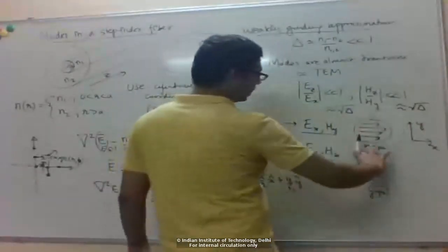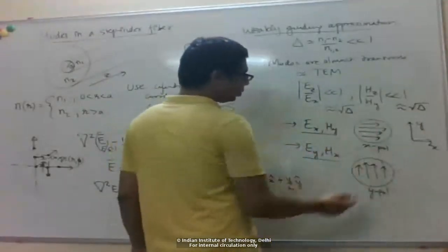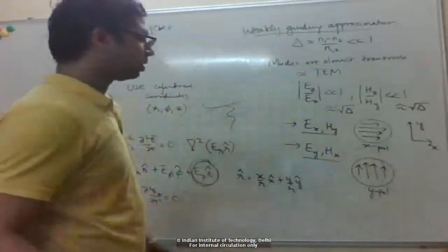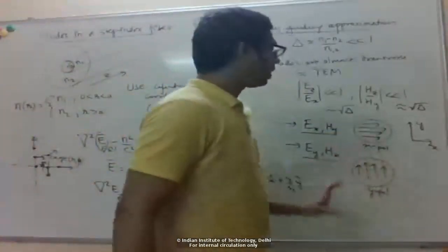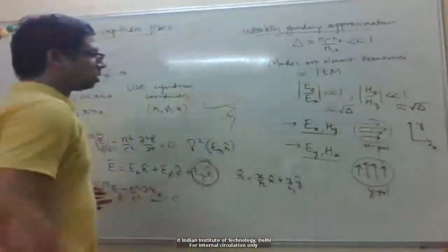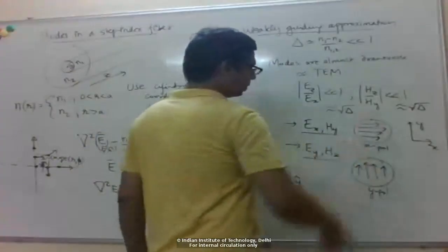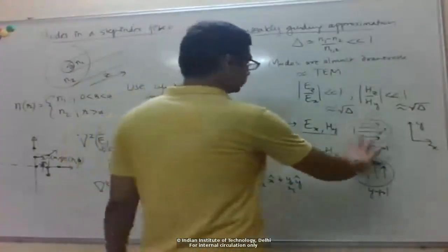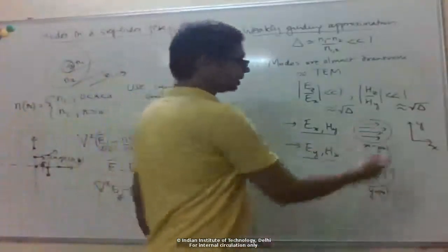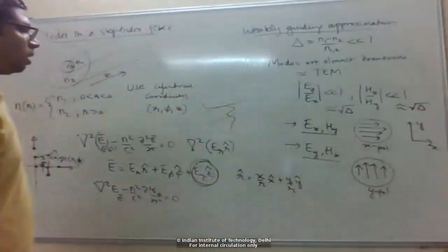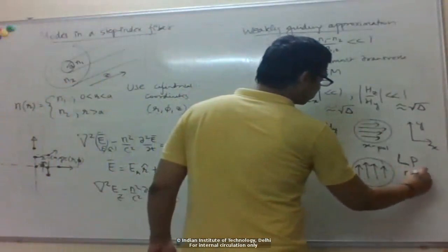Right, and because of this cylindrical circular symmetry, both these modes should be identical in terms of the propagation constant and effective index. The properties should be identical because this is just a rotation, and the structure is invariant on rotation. So these two modes are the same in terms of everything else, like their mode properties, just the polarization differs. And any superposition of these two modes will also give me some other polarization. So the modes we solve for are known as LP, or linearly polarized, modes.